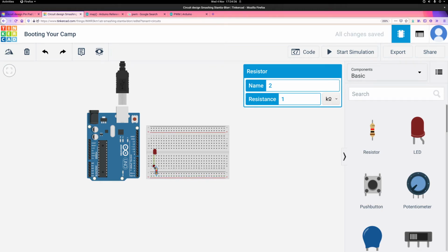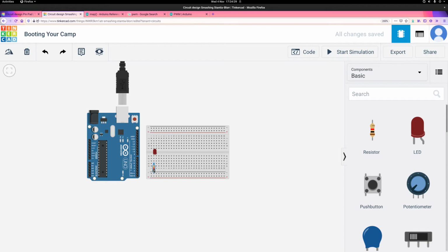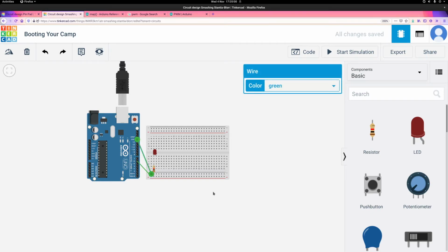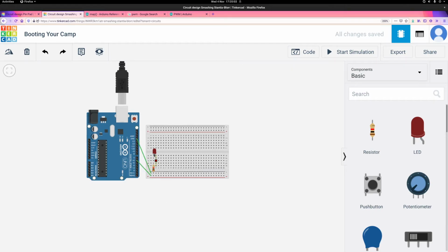And well, we'll do it the other way. So we'll connect the negative end to the resistor, and then we'll connect 6, which is our input. This is the one that'll turn it on and off. Yeah, we'll do full power. Why not? And our negative rail, of course, needs to go up to ground, which is also a ground here. So ground there, as well as 2 over here. They're kind of all over the place on an Arduino. So there we are. Now I can turn on and off the power with pin 6. And to do so, we just need to complete our circuit by taking this over here to the positive voltage. Wonderful. Okay, so that's our same circuit we had earlier.